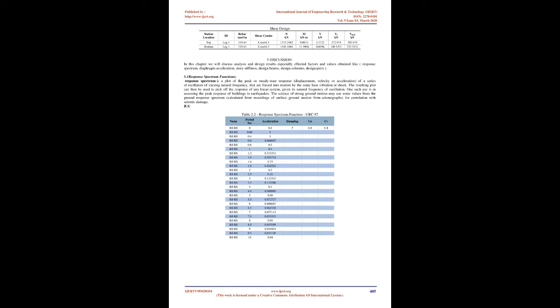All the values are within the limits as per code requirement. As the height of the story increases, the displacement values too gradually increase. The top story has the maximum displacement value in both X and Y directions. For dynamic analysis, story displacement for G+10 and G+25 buildings are 22% and 26% less than the corresponding values in static analysis.